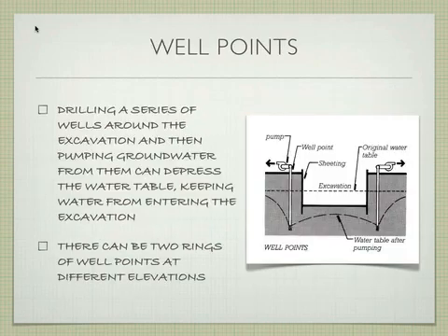Okay, so well points are a good solution that's not quite a sump pit, but does virtually the same thing. So we have our excavation, and what happens is we're going to drill a ring of wells around the site, and they're going to be below where the water table is. There's the original water table. And we're going to start sucking out of each of those wells. And as we suck out of each of those wells, the water table is going to dip. It goes back up in the middle, and then dips here, so that the water table goes down because you're pumping all the water out.